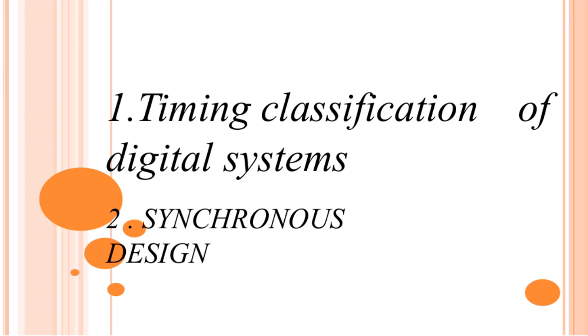Next, we focus on synchronous design, which is a common approach in digital systems. In synchronous design, all changes in the system are coordinated by a clock signal. This clock ensures that all parts of the circuit update their states simultaneously, which greatly simplifies the design and timing analysis. By using a clock, synchronous systems achieve reliable and predictable behavior, making them easier to test and debug.